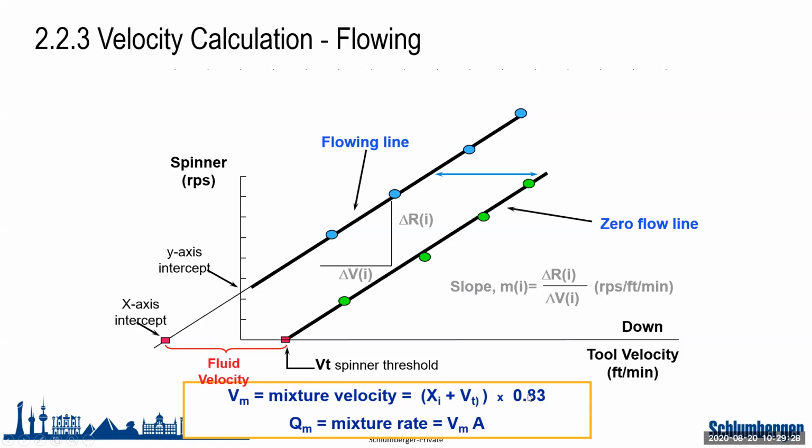This number is very common to appear in literature, especially in books that are old, but this is what we call the velocity profile correction factor. The interpretation softwares are taking the velocity profile correction factor based on Reynolds number, yeah? And as we saw, Reynolds number has several variables that we are also taking from measurements and from inputs. So in reality, you will not have always this 0.83.